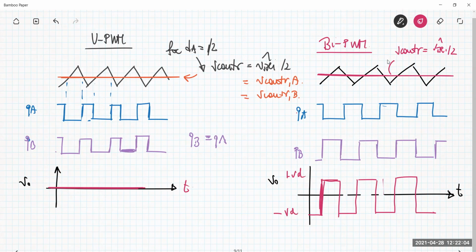I think that you understand the concept. So it means that you have this positive part, which has the same value as the negative part. So the average value is null, as it happens before. But in a unipolar pulse width modulator, an average value which is null is obtained by considering a null waveform of the voltage VT.